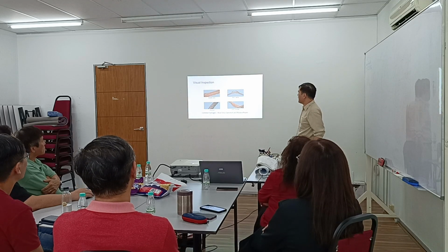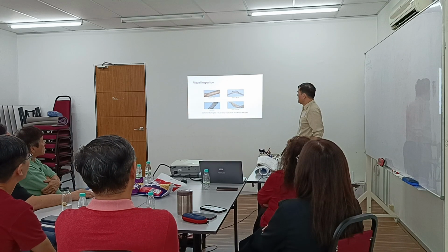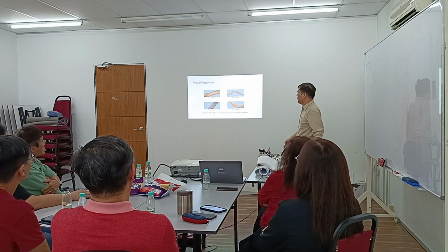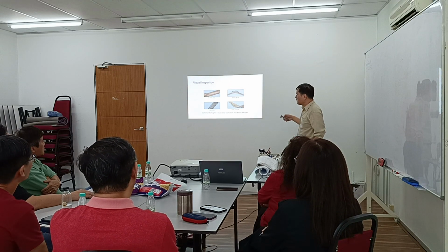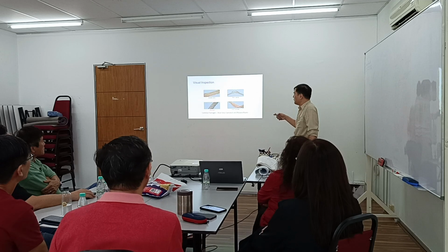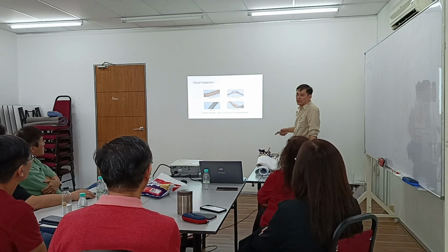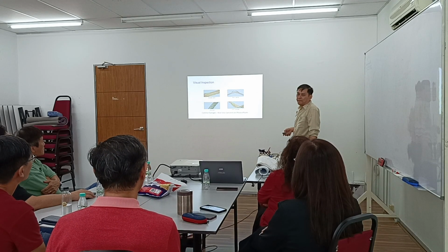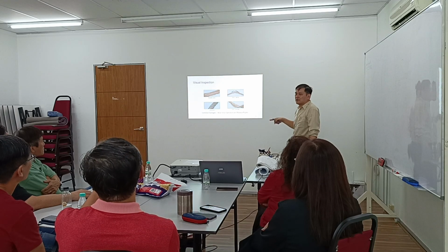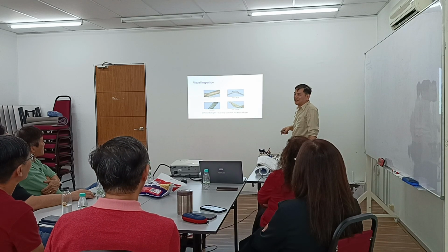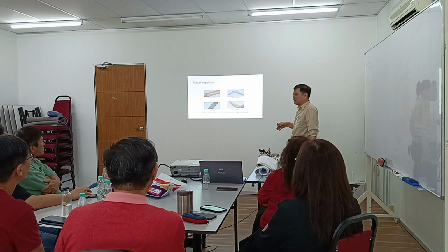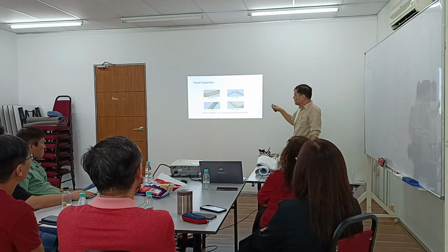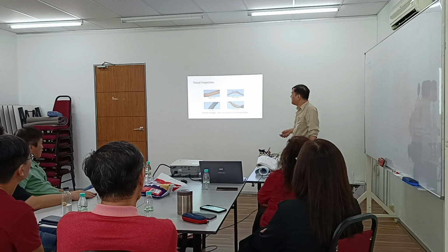So this is the visual inspection: broken wire, bird caging, corrosion, heat damage. This kind of common damage, you must stop operation and replace the rope. It cannot be compromised. Although we say minimum 3 ropes, and the ropes will not simply break, it cannot be compromised at all.